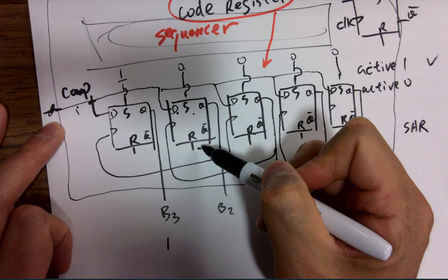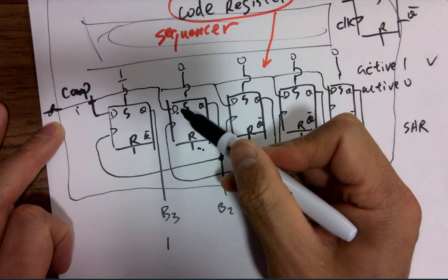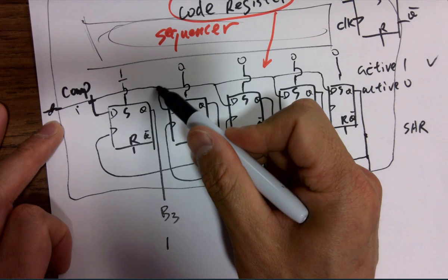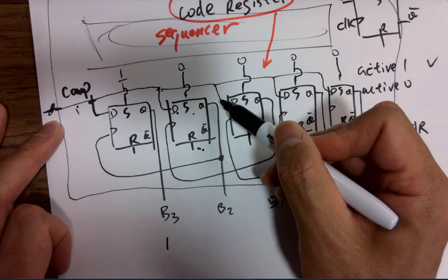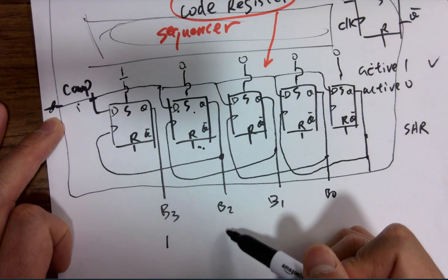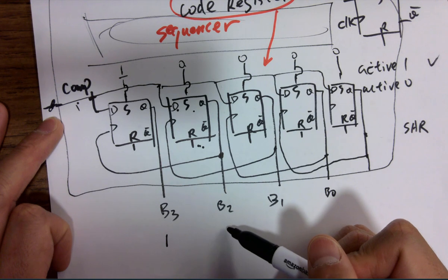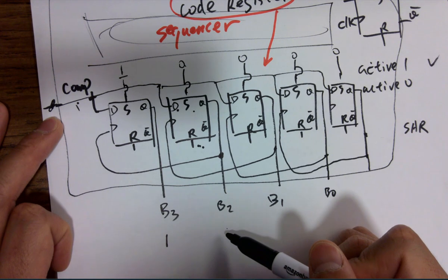So it should be a normal D flip-flop. So the comparator's input to the D should be sent to Q, so it shouldn't always be 0 anymore. Is that the case? It'd be ambiguous, because it would be whatever the comparator's output is.